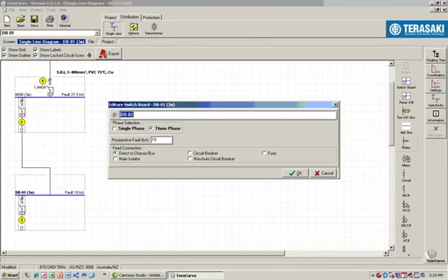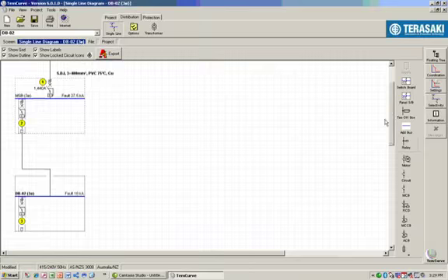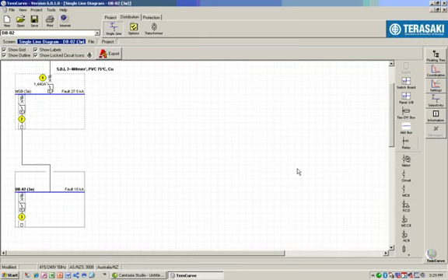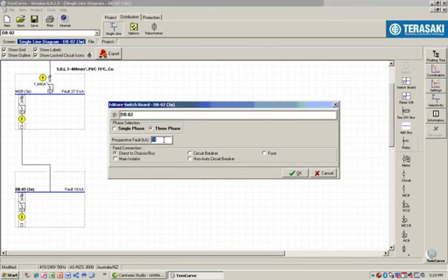DB02. The fault level calculations, you don't always need to make use of that aspect of the software. You can just nominate the fault current at that particular point in the installation, like so.